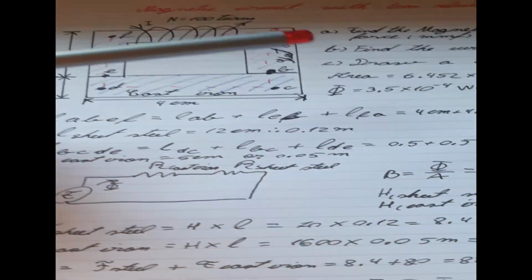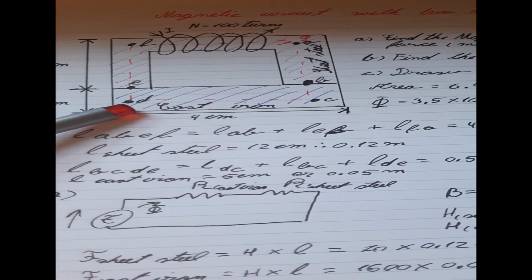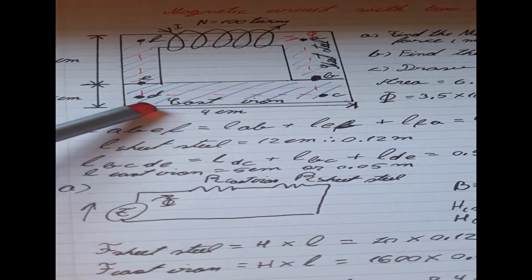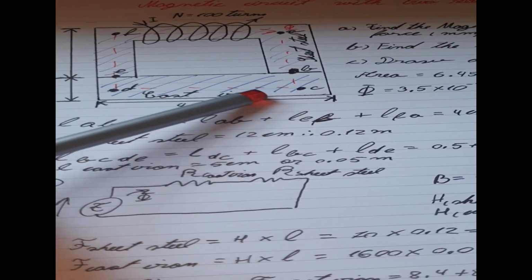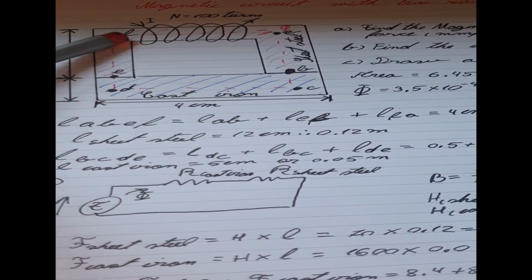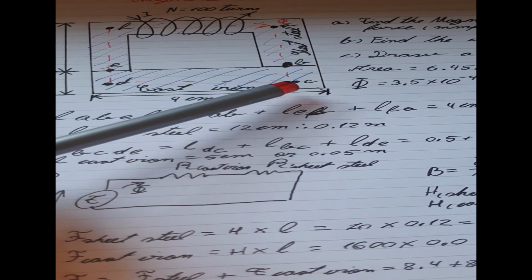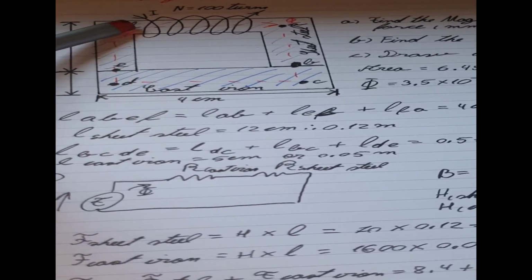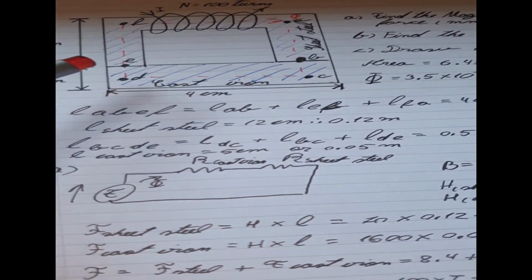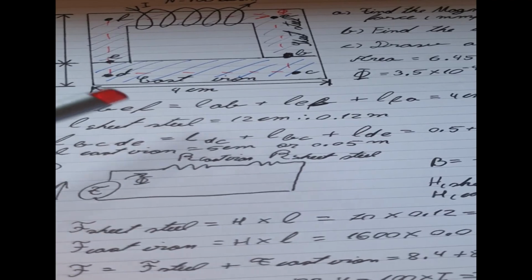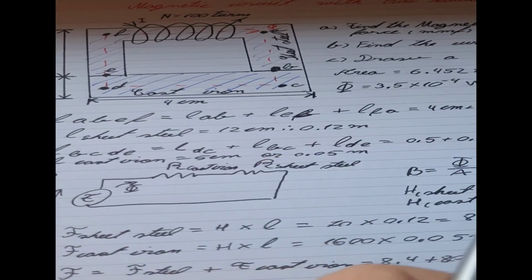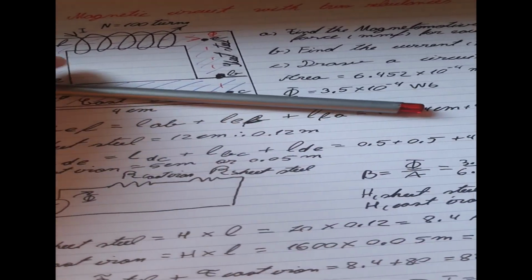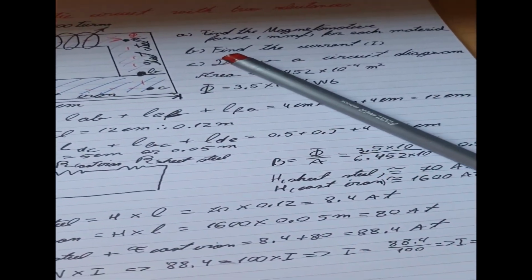And I hope you understand the steps, because basically the first step is to draw the flux, which is going in this direction. The second step is to do the dots for each material, where the material starts, each corner of the material, and where it ends. And then, very importantly, the third step is to calculate the length of each material. After you calculate the length, the only thing we'll have to do, sorry about this, the LED went off.